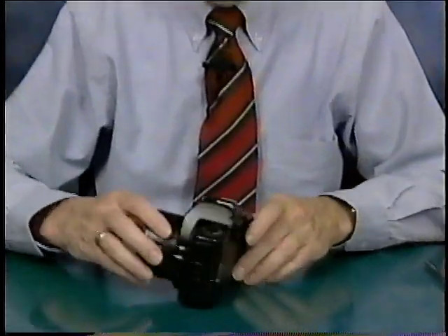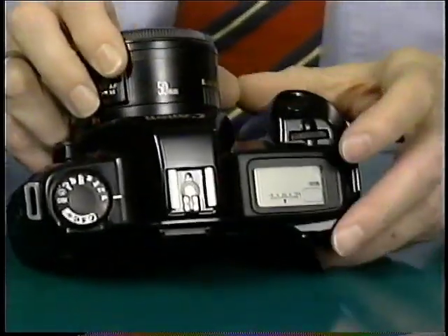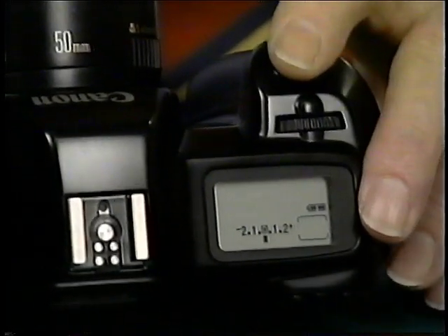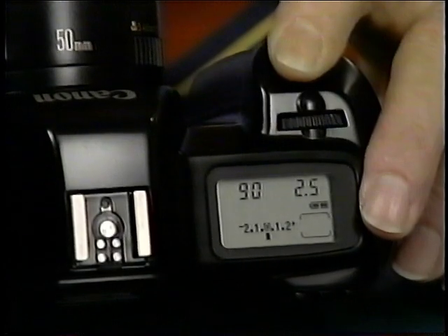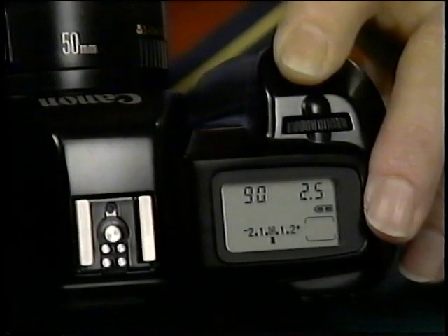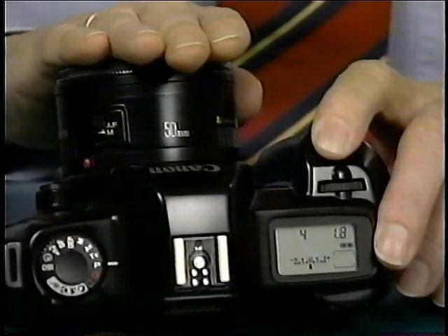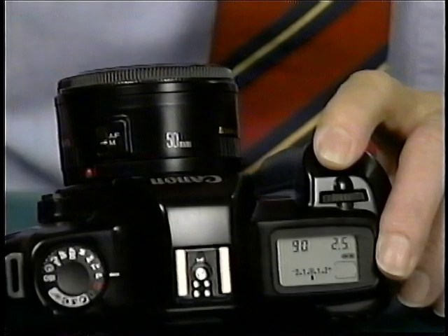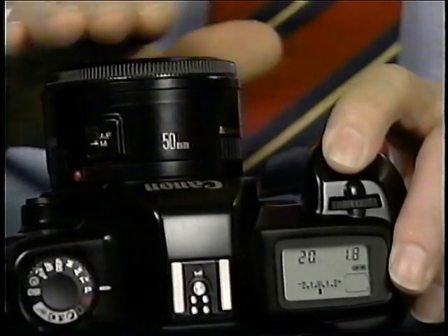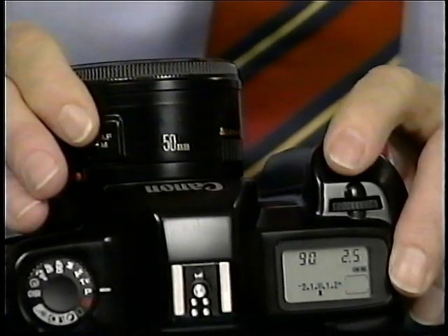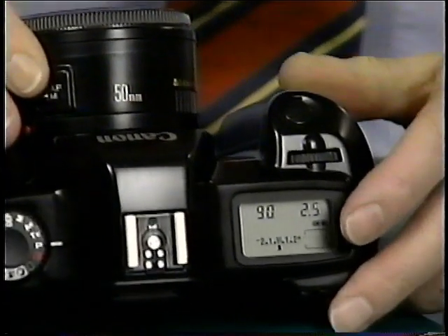Testing exposure systems on single lens reflex cameras is relatively easy because most of them display the exposure. First of all, the metering system should respond to changes in light, and that should be displayed when one presses the release button a half stroke. The display shows a 90th of a second at f2.5. If I cover the lens with my hand, that drops significantly, which indicates that the metering system is working. You should get some type of response when you go from light to dark. Sometimes it will require a second press of the release button, depending on the camera.